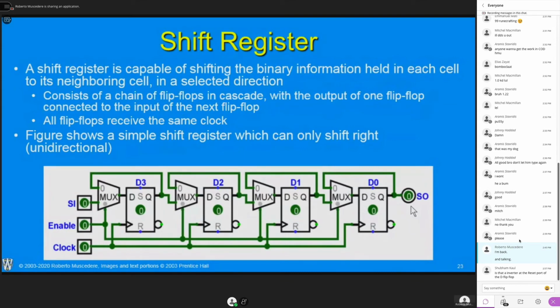In fact, the only thing that's not being sent serially in your CPU or your computer's motherboard is the connection between the CPU and RAM. That's the only thing that's parallel. Pretty much everything else is done serially. And it's done that way to minimize cost and increase performance. Now, when I say minimize cost, it's parts. We're not talking about design time. Design time is high. But for parts, one wire is definitely cheaper than 8, and circuit boards get smaller. Packaging gets smaller. We don't need as many input pins on a chip, but the design time is certainly greater.